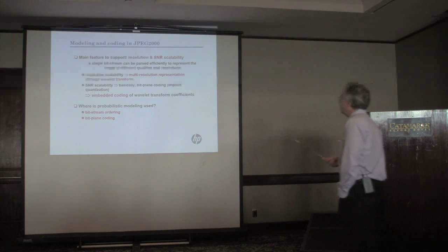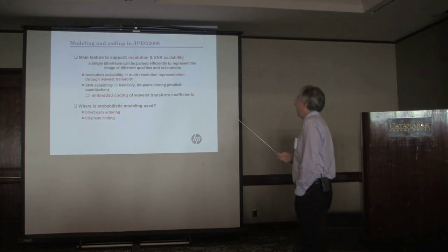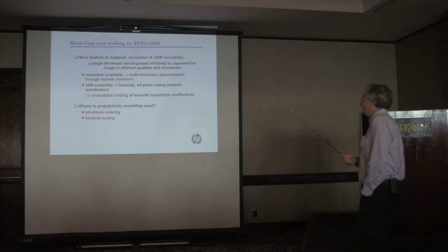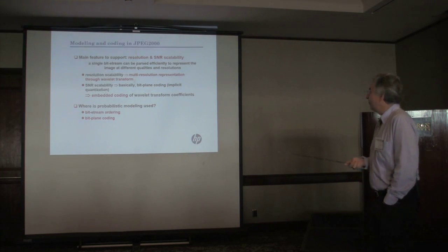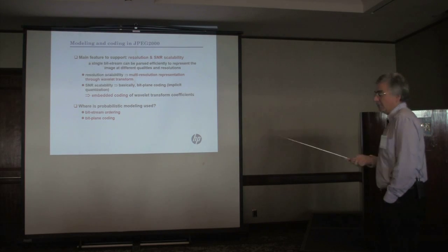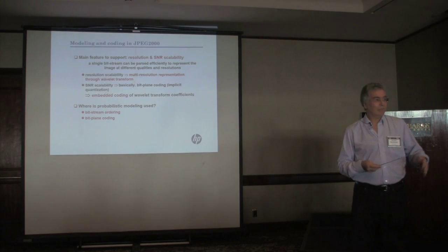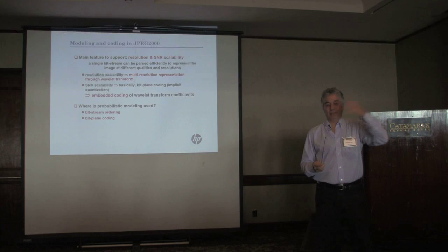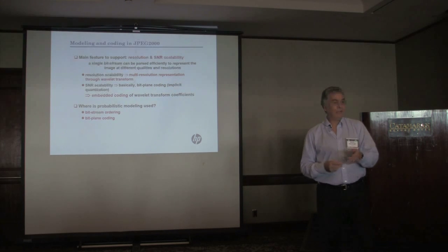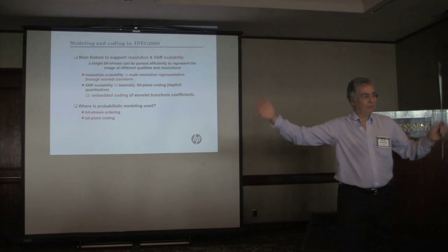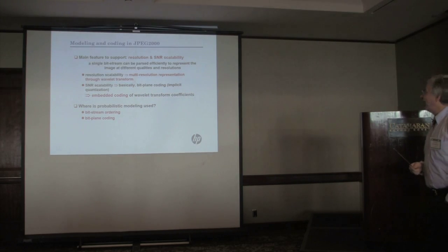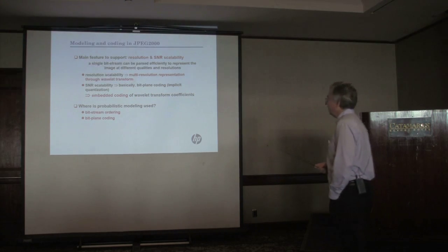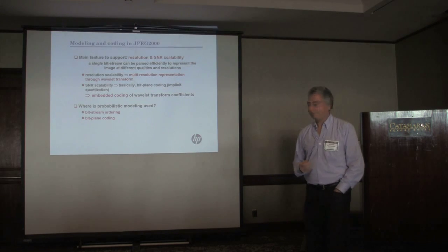What I'm going to talk a little bit about, because we had some involvement there, is SNR scalability. What was done in terms of SNR scalability at the time was basically bit plane coding, which is an implicit quantization. So you send bit plane by bit plane, and you can cut whenever you want, so as to have different qualities of your data according to your resources.